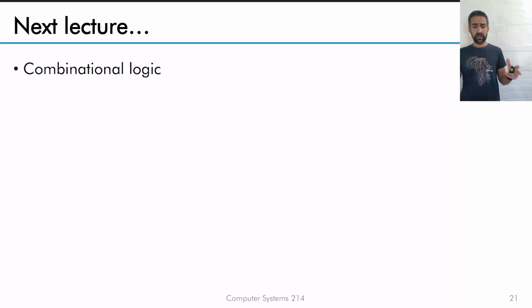Right, so that's really a short lecture, but it's a very important lecture. It's important to understand how this works and where your logic gates come from. It's about understanding the cow behind the milk. You need to understand where this thing is coming from, so that you can use it properly, and so that you can understand concepts like power consumption, so that you can understand concepts like the pin is floating. So when you see a pin at a weird voltage, then you have to ask yourself, what's going on here? And then you can think back, oh, probably the inputs are not connected, so I'm not driving these transistors properly.